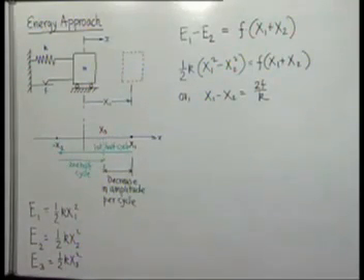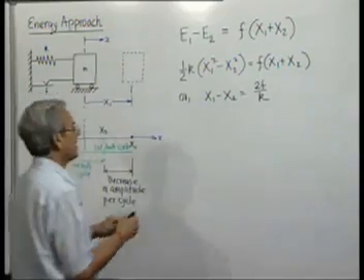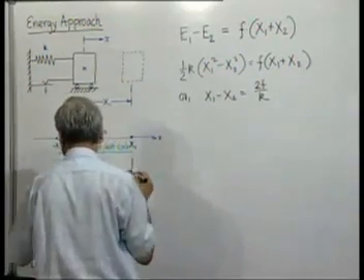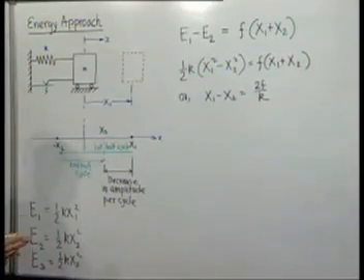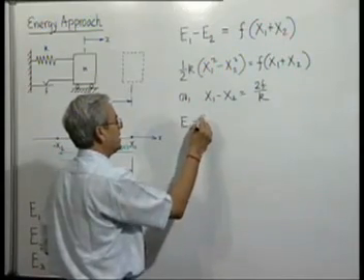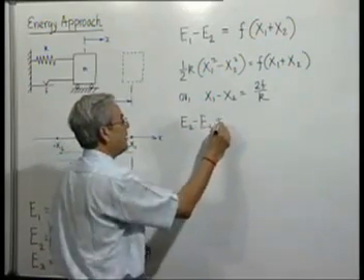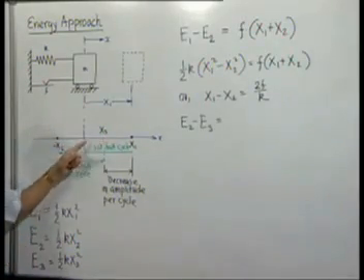So straightforward, we get the decrease in amplitude, or the extreme values of the displacement in the first half cycle, is straightforward: 2f by k. Similarly, if we do this for the next half cycle, the energy decreases from E2 to E3. So E2 minus E3 is the amount of work lost by friction, which is the friction force into this distance travel.